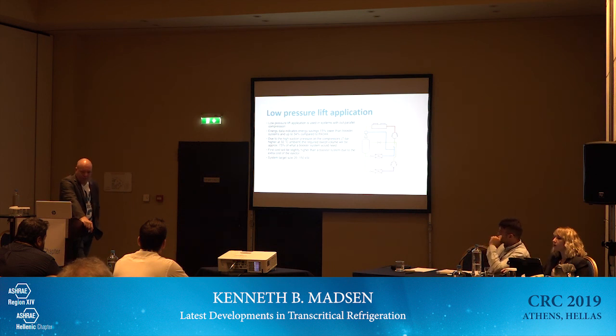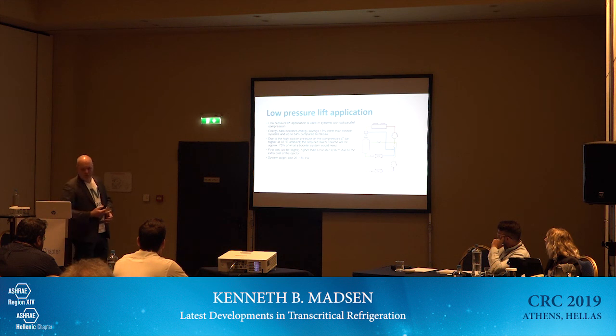But as you can see, we have a gap on smaller systems where we basically do not have a technology that can bring us down into warmer climates because we are somehow stuck with booster technology. We cannot use parallel compression because it's too expensive. We cannot use high pressure lift ejectors because that is also too expensive. So we need something else here. And this something else could be a low pressure lift ejector that we are basically doing quite a lot of testing on at the moment.